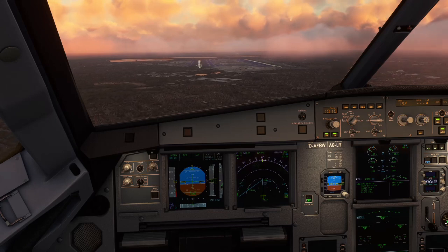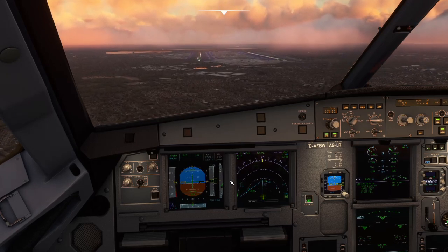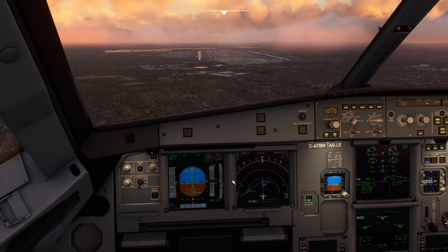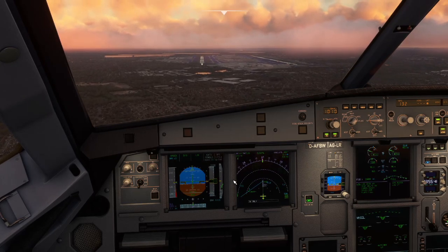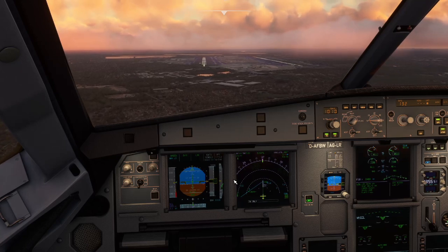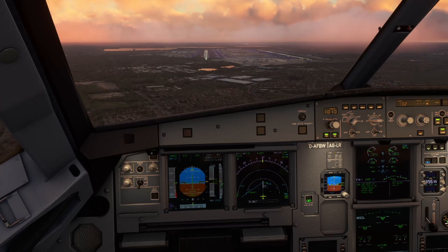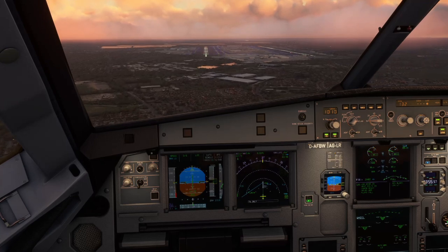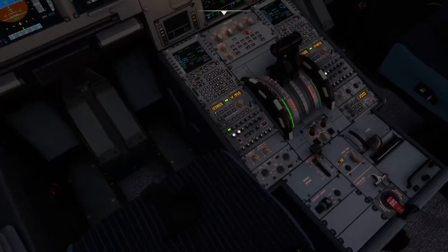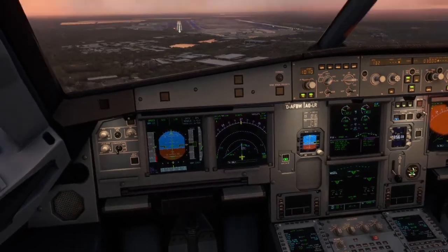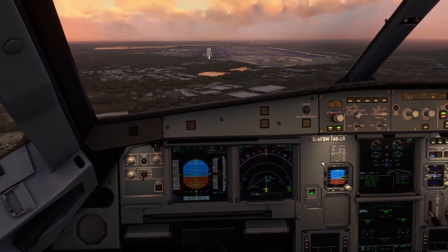1,000. Anyway, here we are at 1,000. We've got gear down, flap full, checklists are all complete. Everything's pretty good. We are stable. The intention of showing this was just to basically demonstrate anyone could do this, to be fair. So I'm going to let it autoland itself. I've got auto brake low, the spoilers are armed, and the jet's going to literally land itself. It's going to be happy days.